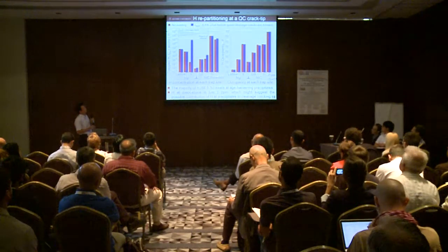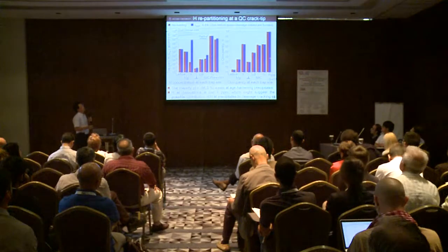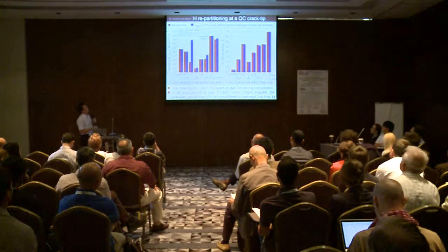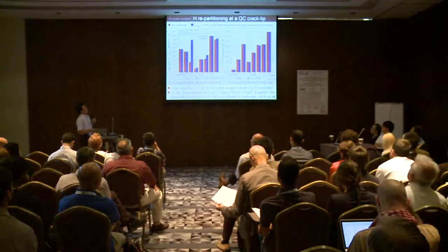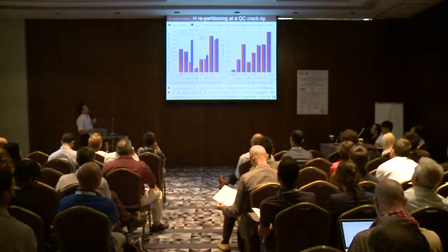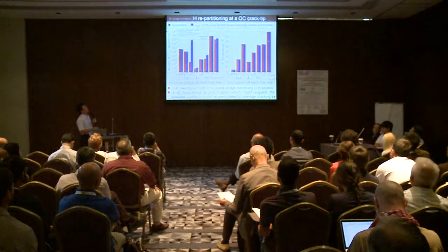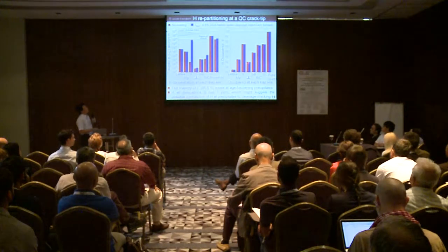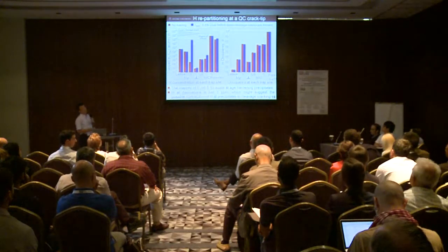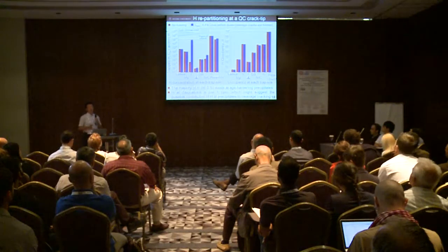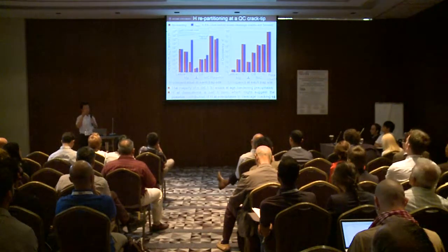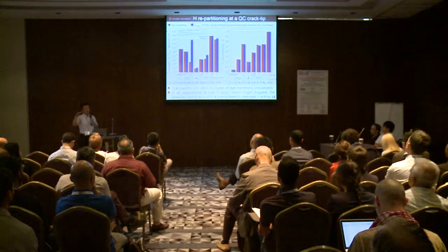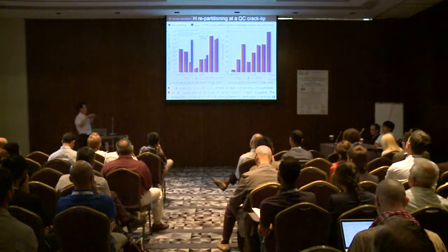And if you take a look at the dislocations, we have a fairly low hydrogen concentration at dislocations. If you take a look at the hydrogen occupancy, nanovoids and microvoids, it is almost 100%. And then vacancy, intermetallic compound particles, and precipitates, it is roughly 1%. And then dislocations, it is just 1 ppm, which means we may be able to find just one hydrogen atom over 1 million possible trap sites.